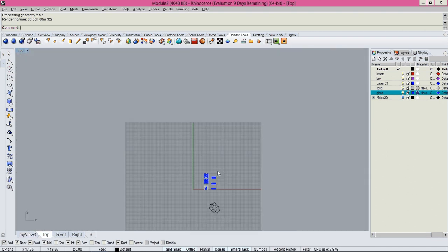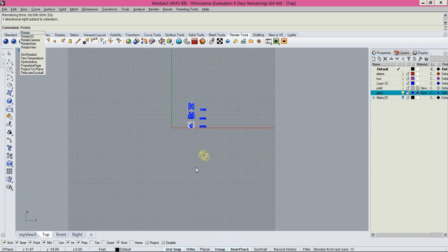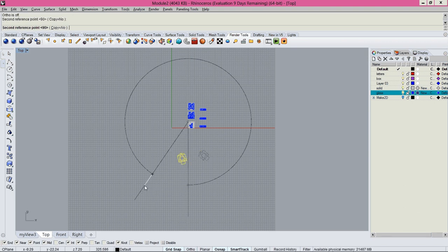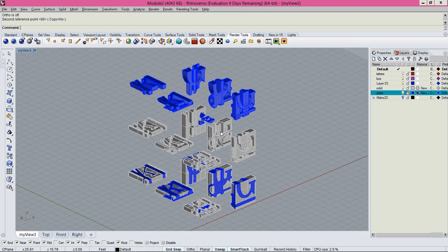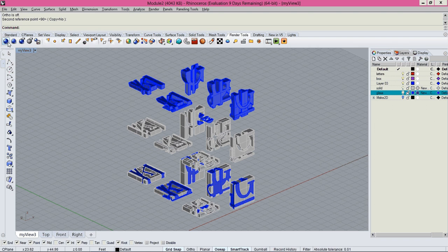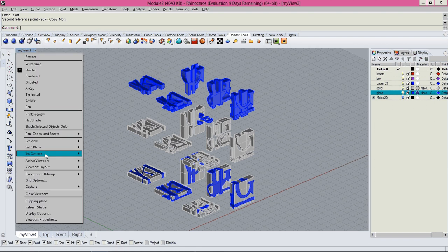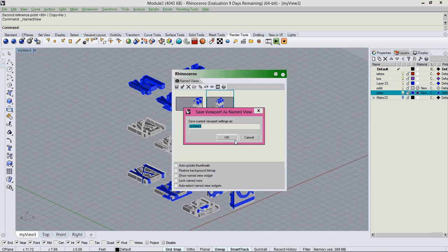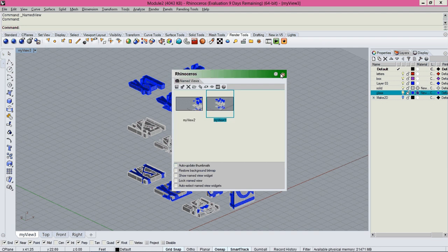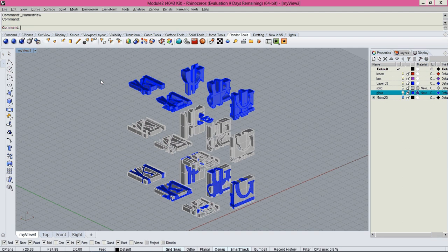Probably even in the top view we could rotate this because it was throwing shadows. I'm rotating this a little bit, going to the view, and probably this one makes more sense. So I'm not going to render, but basically, as you know, you have to save the view, name view. You can always press this one and save it again, say okay, yes, you close, and render it. It should be nice. So I'm not gonna leave it rendering, I will show it at the end.